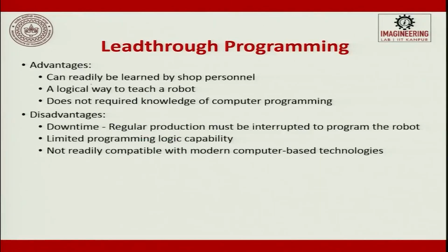The advantage is that it can easily be learned by the shop floor man. It is a logical way of teaching a robot and does not require knowledge of computer programming. It is something a semi-skilled laborer can teach. The disadvantages are the downtime: regular production must be stopped to program the robot, there are limited programming logical capabilities, and lead through programming is not readily compatible with modern computer-based technologies. Once you have done lead through, if you want to edit that programming, it is very difficult. That is why we use simulation and offline programming.